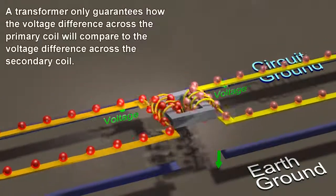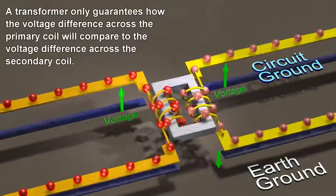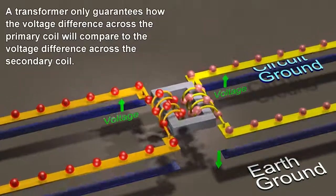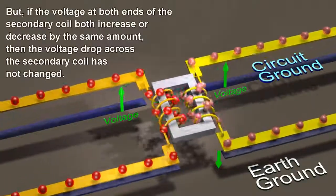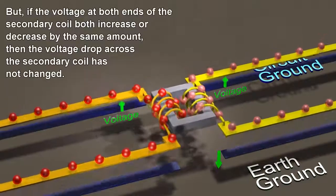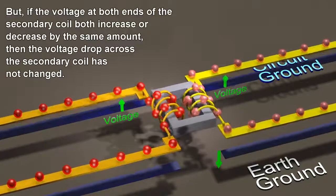A transformer only guarantees how the voltage difference across the primary coil will compare to the voltage difference across the secondary coil. But if the voltage at both ends of the secondary coil both increase or decrease by the same amount, then the voltage drop across the secondary coil has not changed.